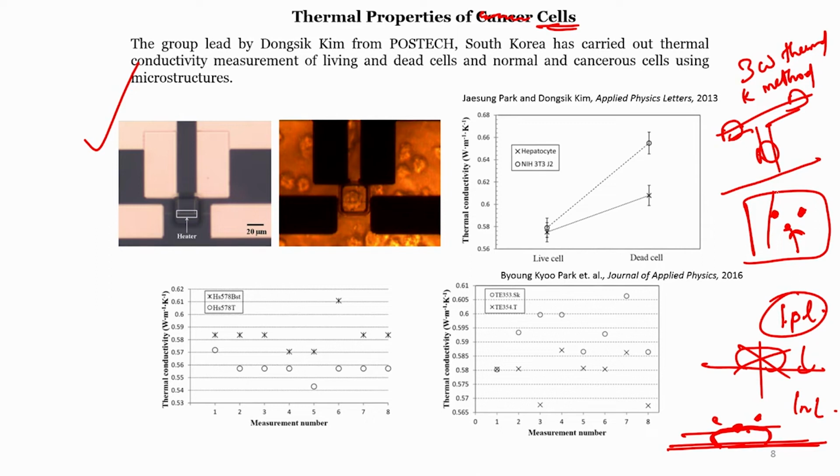Okay. Now, when you simply heat a point, this is a very small volume, right, 1 picoliter, and usually one cell's dimension is around 10 nanometers. If you heat it very quickly, this heat can transmit and reach the bottom surface or the liquid that the cell is on, which can actually interfere with your measurement of the thermal conductivity.